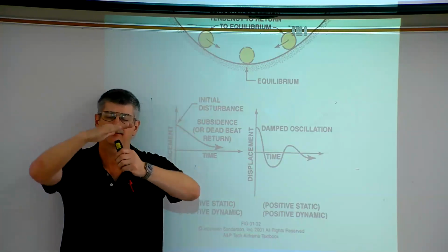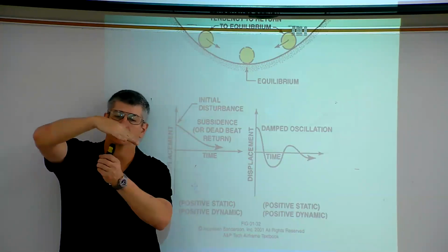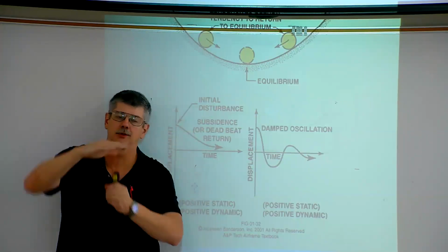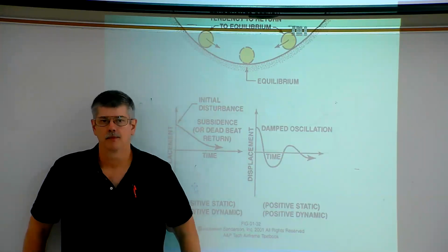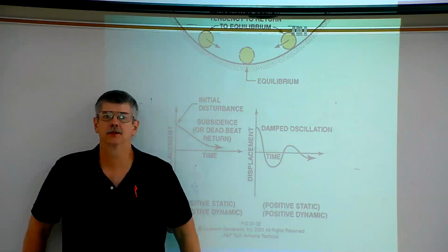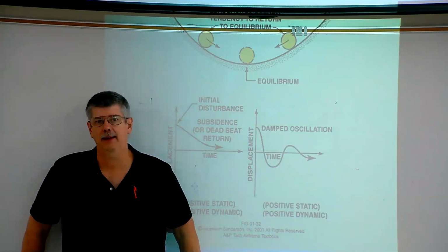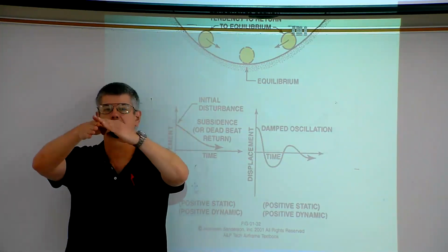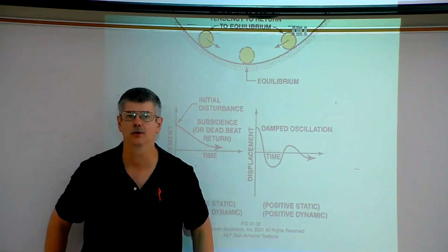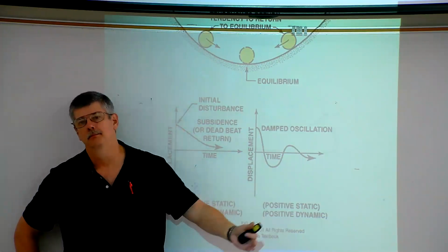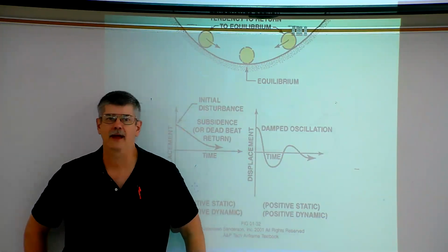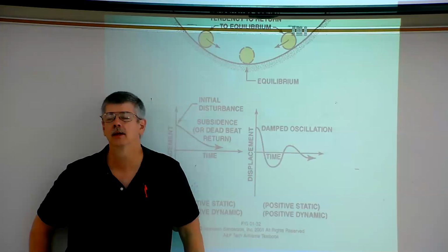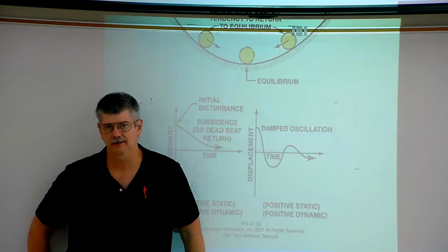So if the aircraft does roll, the weight will want to upright the aircraft. The other thing is what's known as aerodynamic blockage or fuselage blockage. When the aircraft rolls, it's going to slide towards the low wing. The fuselage will block the air trying to hit the low wing and thus reduce its lift.